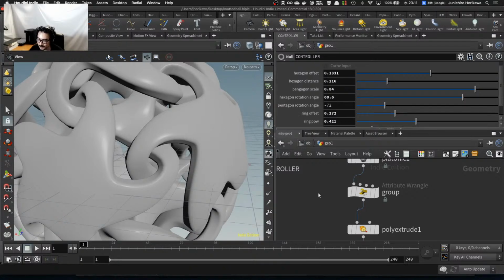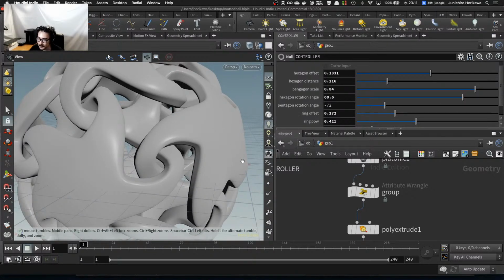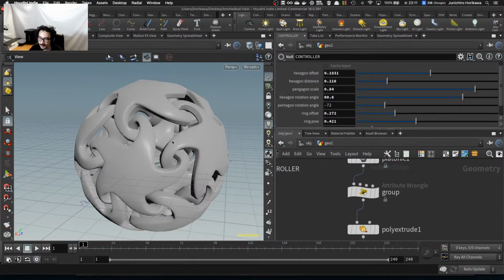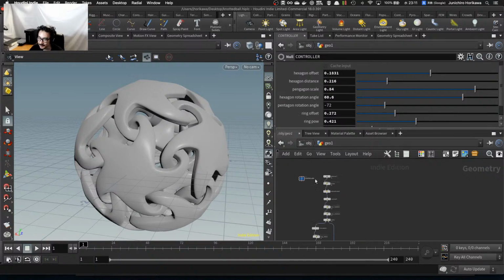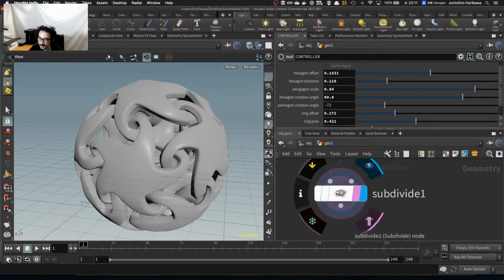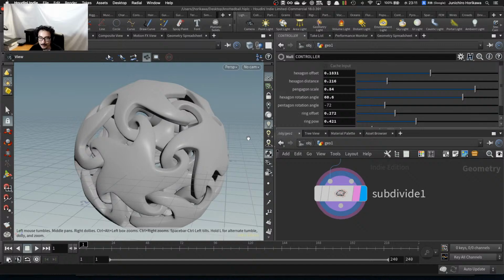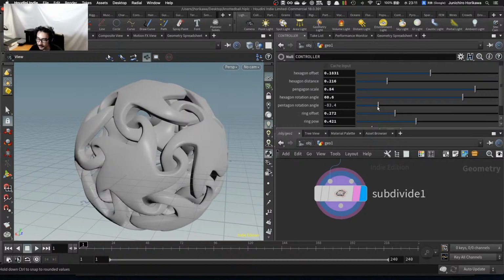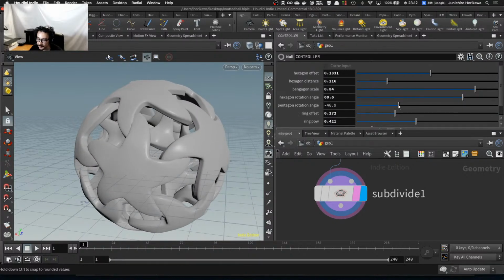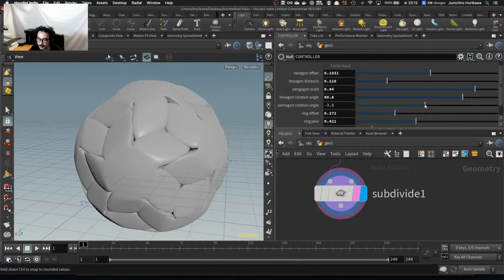And since this is a Houdini procedural modeling tool, you can apply a whole lot of additional stuff on top of this geometry right after this one, like creating Voronoi holes in it or something like that procedurally, which makes it even more interesting, I think. So I hope you would try that out for yourself. For today, I just showed how to create the base shape parametrically. This is also interesting.